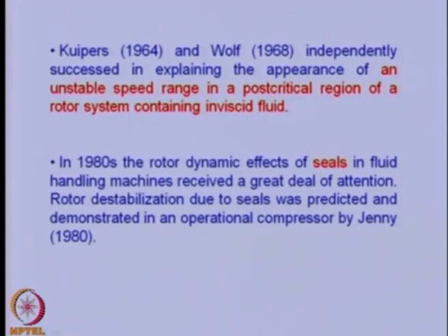Kuipers in 1964 and Wolf in 1968 independently succeeded in explaining the appearance of an unstable speed range in the post critical region of a rotor system containing inviscid fluid. In the 1980s, the rotor dynamic effects of seals in fluid handling machines received a great deal of attention. Rotor destabilization due to seals was predicted and demonstrated in an operational compressor by Jenny in 1980.